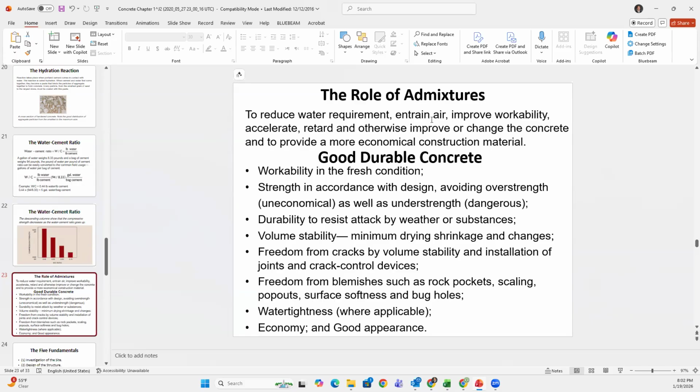So can you say that if you're going to deal with colder climates, you do want concrete that has more of these microscopic bubbles in them? Yes. Okay. All right. You want a strong concrete with some ability for that concrete to expand and contract.